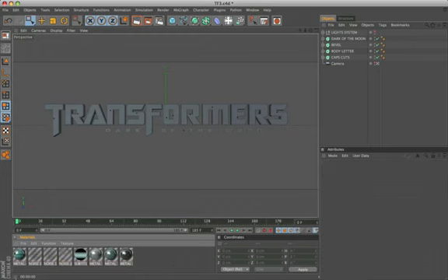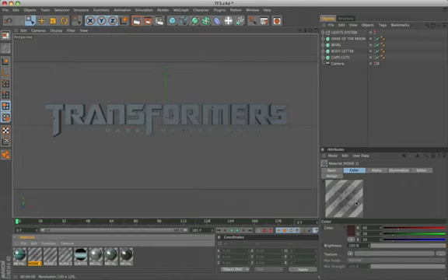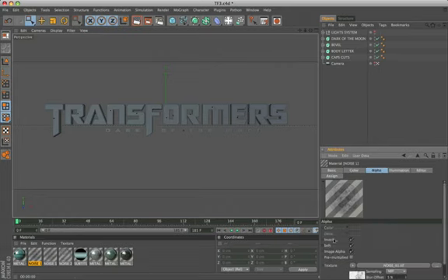The material Metal 4 is a duplicate of the metal material, to which I applied a Metal Sci-Fi texture, and will be applied to the body letter. The materials Noise 01 and Noise 02 have the alpha active. Through a black and white texture, we can get different effects of dirt on our letters.